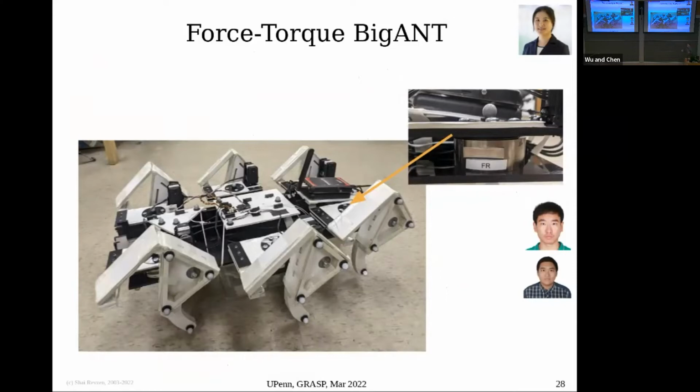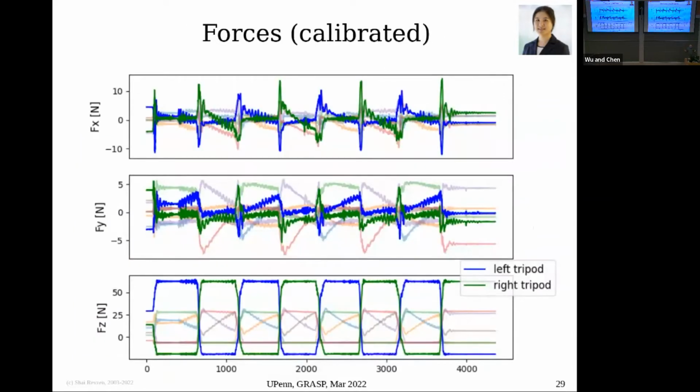So we can actually measure the ground reaction force of every single leg as a function of time and find out whether we got the right answers for the wrong reasons because somehow the Coulomb forces combined to look like viscous friction, or whether the friction model was wrong, which you can't tell unless you can actually look at the contact forces. Turns out calibrating that sort of system is very, very hard. And it took my grad students about a year and a half to do. But I'm happy to say that it's now nicely calibrated.